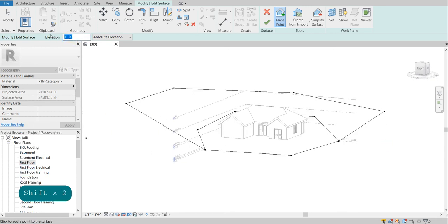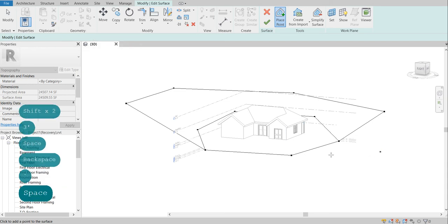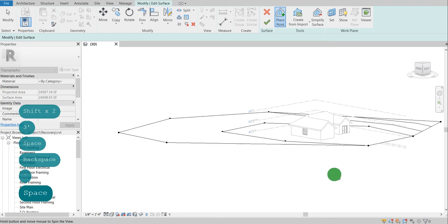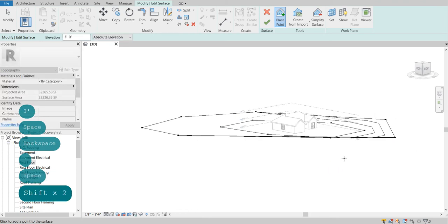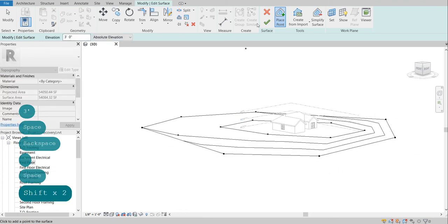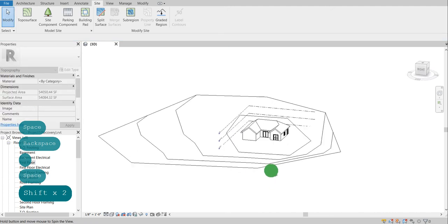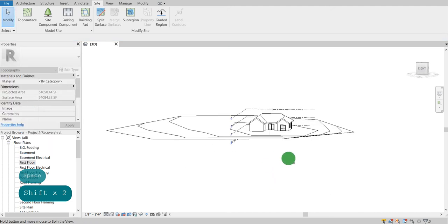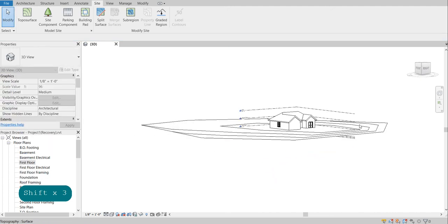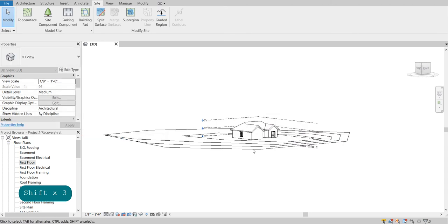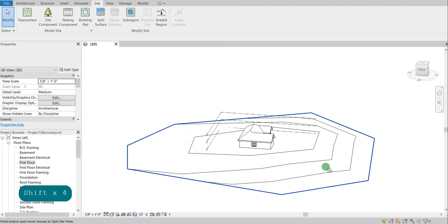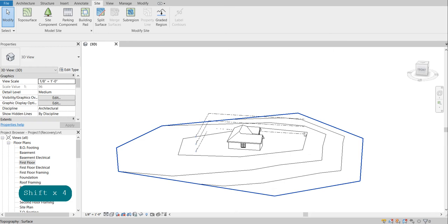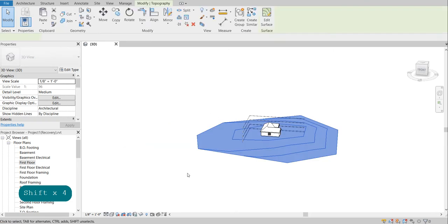Okay, I'm gonna exaggerate here so you can see more. I'm gonna do 3 feet. Okay, and then it starts to create the site. So here we have this weird little site that's tilted up, and basically you just place points on the elevation, and it just creates the surface for you.